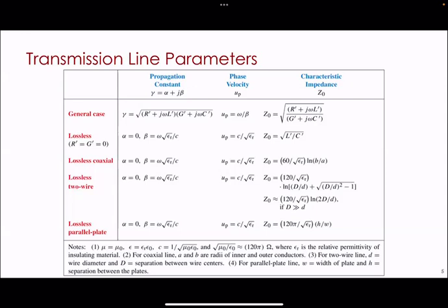That solves half of the puzzle. It tells you R prime equals 0. If the conductors are perfect, R prime equals 0. G prime equals 0 happens if the insulator is perfect. So if I said it's a perfect dielectric or a perfect insulator, or the conductivity of the insulator is 0, that would tell you G prime equals 0. Those are the 3 ways you could be told that it's lossless and that you could use the second line of equations.